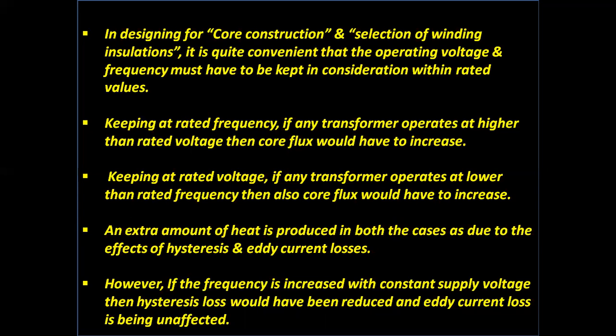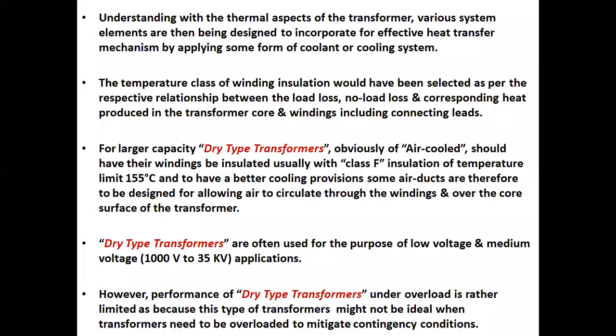An extra amount of heat is produced in both cases due to the effects of hysteresis and eddy current losses. However, if the frequency is increased with constant supply voltage, then hysteresis loss is reduced and eddy current loss is unaffected. Understanding the thermal aspects of the transformer, various system elements are designed to incorporate an effective heat transfer mechanism by applying some form of coolant and cooling system.